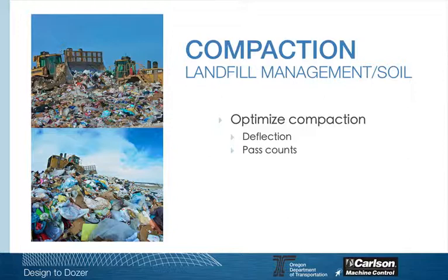Well, it's not real easy to know everywhere you've been, so it can be fairly unproductive and a fair amount of guesswork. So if I roll over a particular area once, twice, 3 times, I need to know exactly where I've been. So application software will color the screen with each pass, measuring and coloring exactly the size of the machine's compaction footprint. So this way the operator knows exactly where and how they've compacted or where the passes have been.